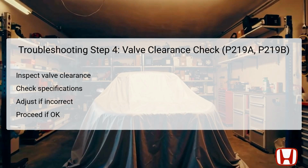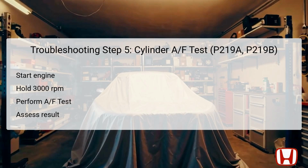step. This process helps ensure that mechanical aspects of the engine are functioning correctly, contributing to the overall air-fuel ratio management. In Step 5, the focus returns to conducting another cylinder AF test with the engine running. After starting the engine, maintain the engine speed at approximately 3,000 RPM, again, ensuring that the vehicle is in park or neutral with no load during this test.